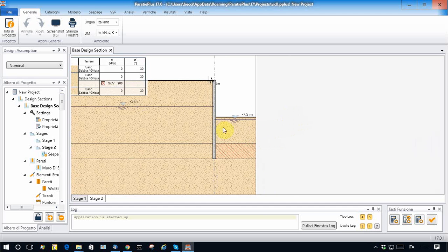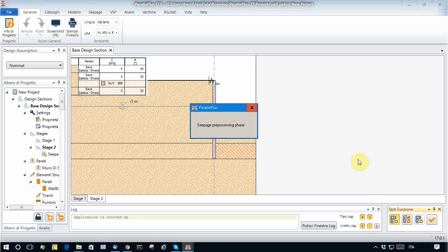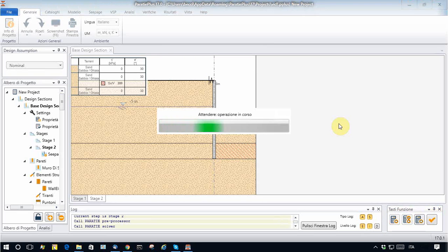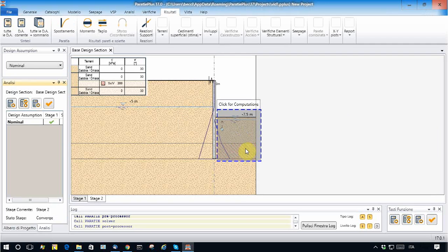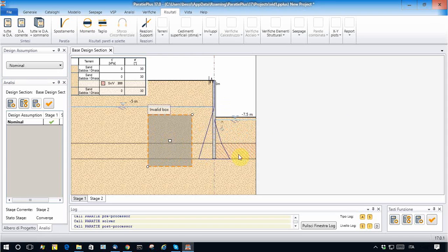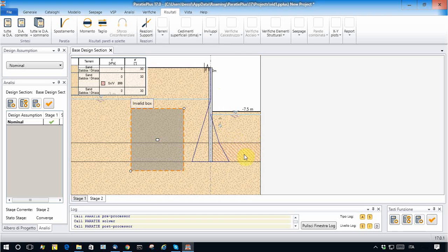In this model, if you remember, we put the soil plug at the sheet pile toe. This is very effective, because normally by doing so you can have a less thick soil plug to guarantee stability, but at the same time you must do extra drilling for reaching this zone. The advantage, as for stability, as for bending moment, especially of the wall, is less.